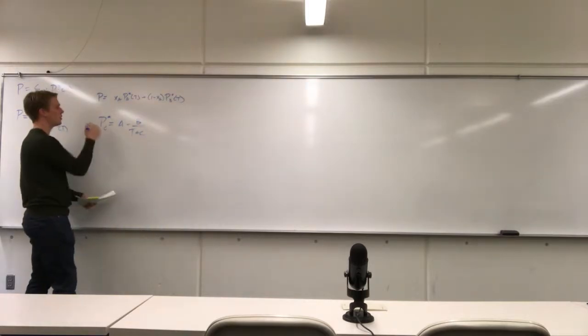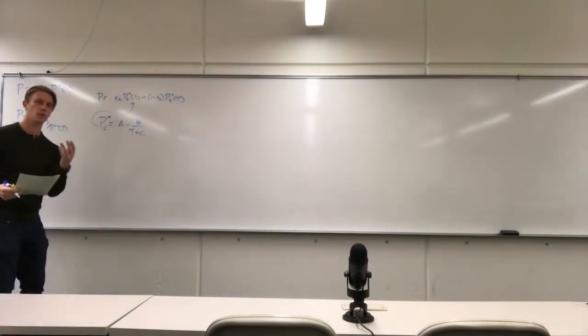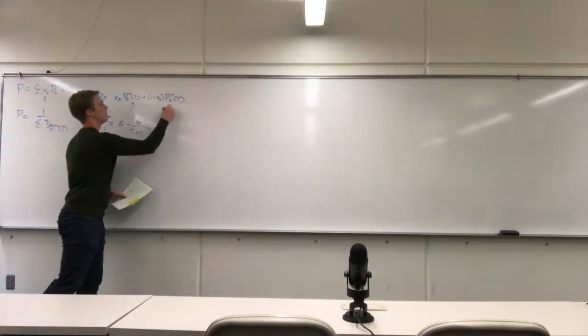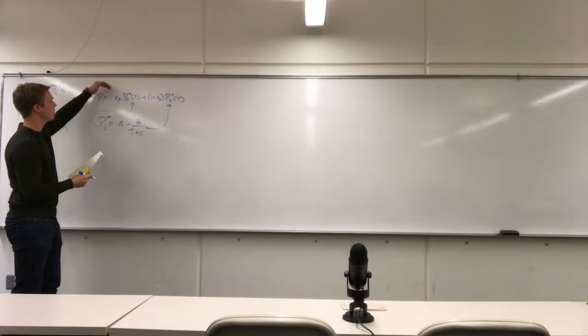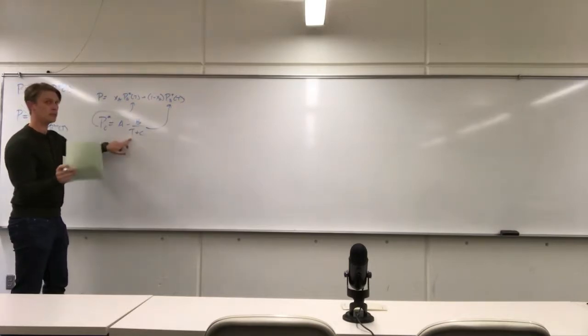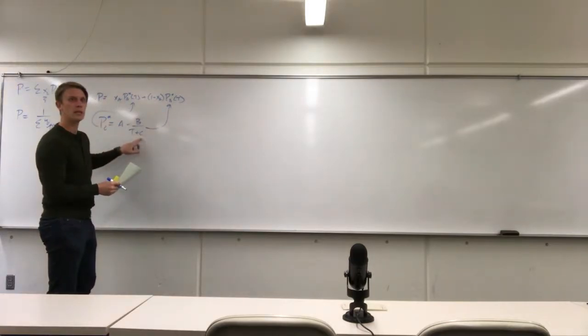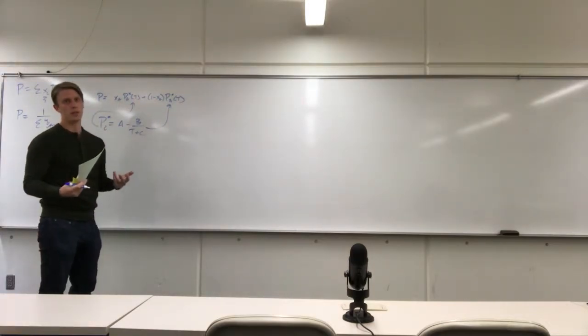we can imagine that we substitute this expression into here. Now we still have one equation and one unknown. Pressure is known, composition is known, A is known, B is known, C is known, T is unknown. So all you have to do is a goal seek, in Excel, for example.